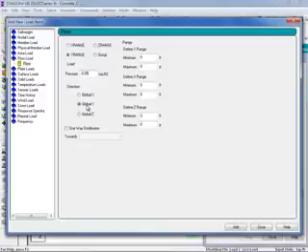Now for a floor load, this doesn't get assigned after you leave this dialog. It actually gets assigned at the same time, and I have several different assignment methods I can do. For this particular model, I'm going to select the Y range option, and I happen to know that the roof level is at a Y equals 14-foot coordinate location.